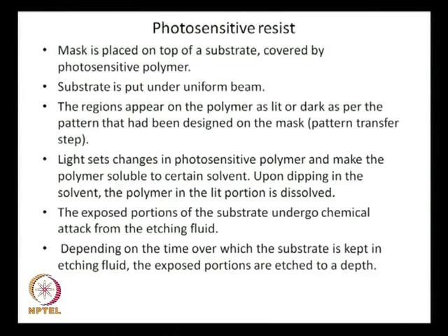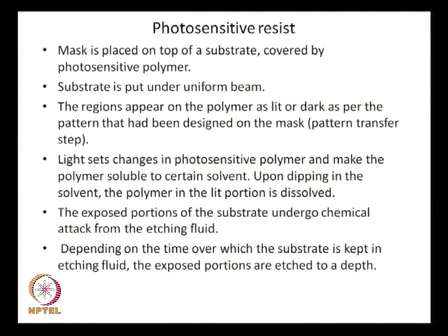So, when you dip this substrate, after the dissolution of the polymer, into the etching fluid, then the etching starts, but the etching happens only in the places where the substrate is exposed. Next, depending on the time over which the substrate is kept in the etching fluid, the exposed portions are etched to a depth. So, how long you keep it in the etching fluid matters. Gradually you see the etching taking place and a depth develops in that channel.